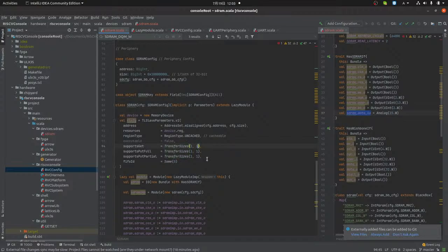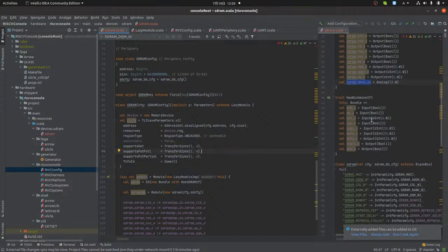Okay, transfer size. So we only support 1 to 4. Why 1 to 4? Because the interface of the wishbone supports up to 32 bits, and it has 4 selections. That means that it supports 1 byte and up to 4 bytes. So this is strictly our stuff. Now, this is executable true, because if we don't put it executable, that means that whatever we put into this memory won't be able to be executed.